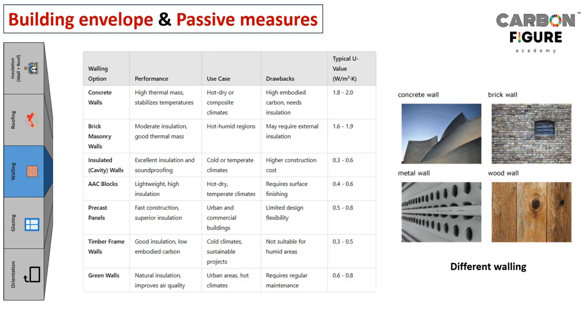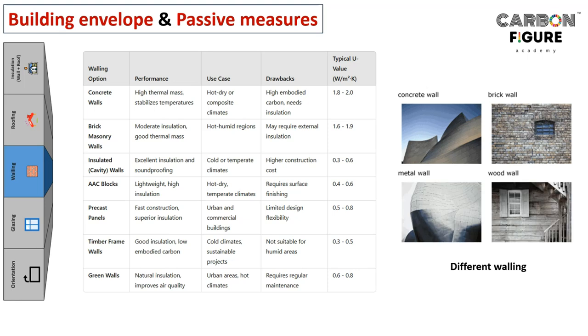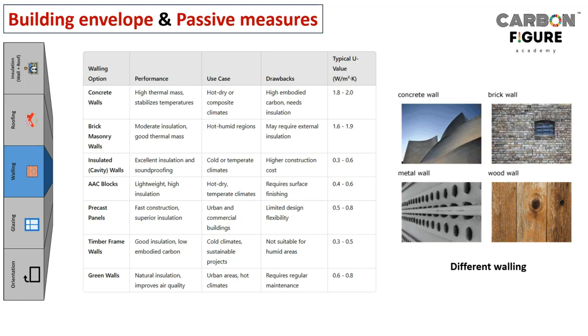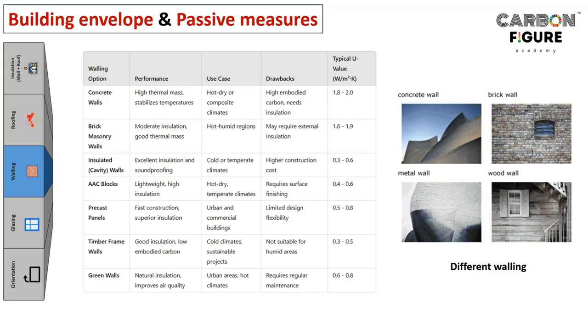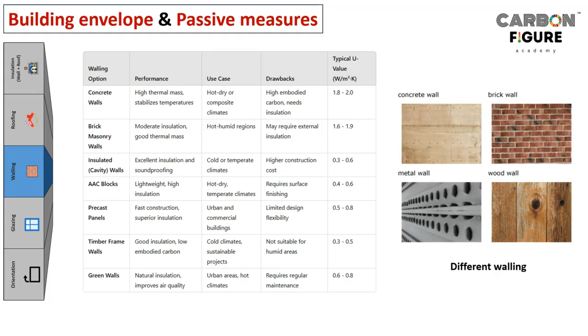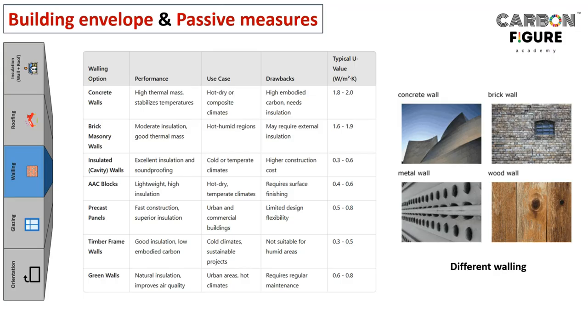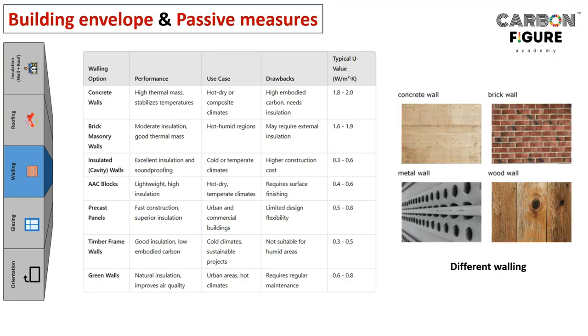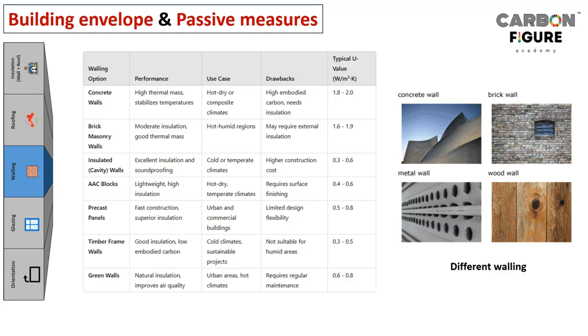So okay, now are you able to understand? This is how the U value will play a role in selecting the envelope material. It could be a wall or glazing or anything, right? If you would like to have a better indoor environment, then you have to ask what the U value is, right? It is typically 1.8 to 2 watt per meter square Kelvin, right?